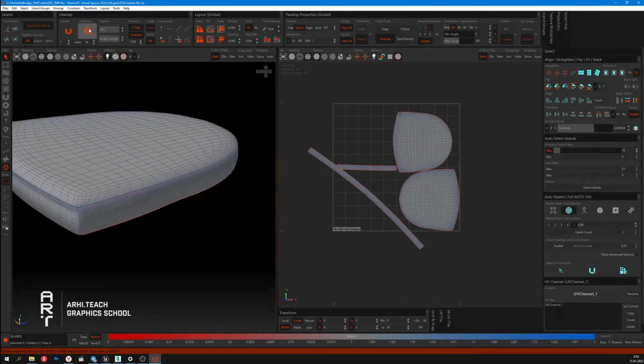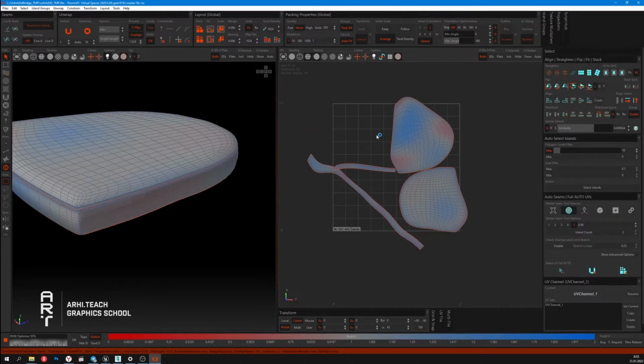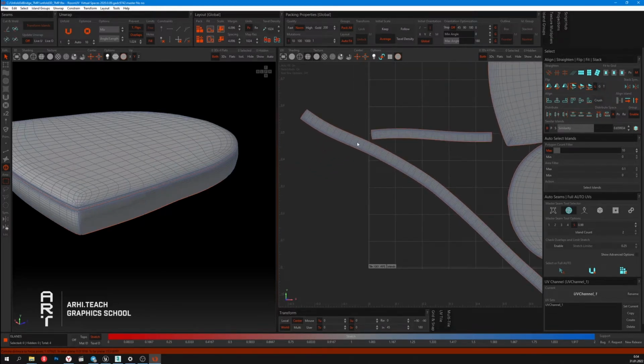The next button is Optimize. It allows you to optimize the unwarped grid in that way, so it would have as few stretches or compressions as possible. To show how this function works, we will distort the grid a bit. Now let's press Optimize. Now we can see that the grid has aligned. You can press a number of times, or point at an element and press a few times.